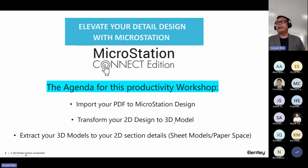Not only that, once you have a 3D model, how you're going to extract your 3D model into a shop drawing or 2D detailing. That is called extracting your 3D models to your 2D section. In Microstation we call it sheet models, or in other CAD applications it's called paper space. I think most of you, if you are CAD users, are very familiar with paper space.